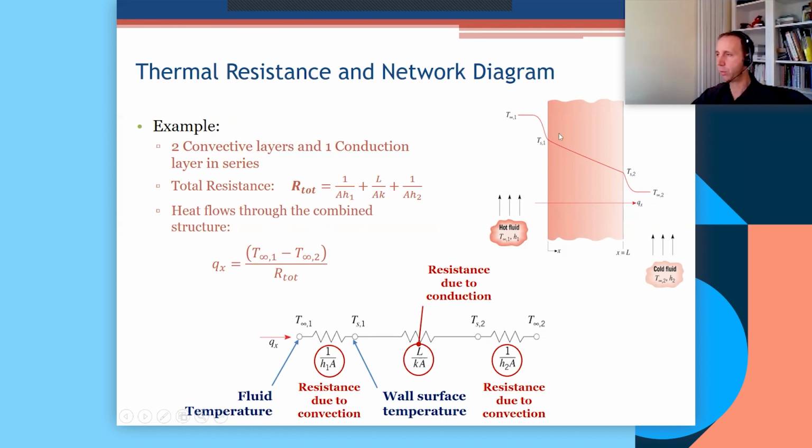So as we travel along that one-dimensional domain, straight line, you will get a temperature difference where resistance exists. Since there's a temperature difference there, you need a resistance. There's a temperature difference here, resistance, and so on. You've got three layers that induce temperature change, so you've got three resistances. The circle represents a region of uniform temperature. Far away from the wall, we assume the free stream is at the same temperature, T infinity 1. Here, far away from the wall, we assume the temperature is uniform at T infinity 2. No matter where you go, if you continue, you still have the same temperature.